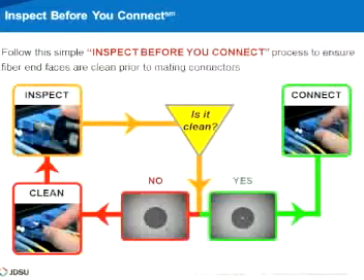So inspect first and determine if it's clean. If it's not, use the cleaning procedure and reinspect again, and continue this procedure until the connector passes satisfactorily.